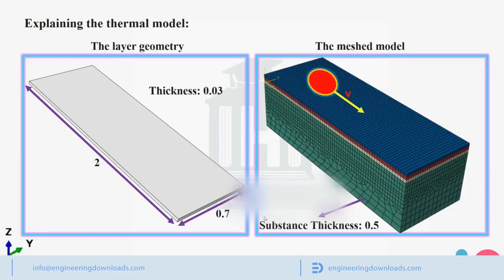In case you face a convergence problem in thermomechanical analysis, a possible option to fix the problem would be using the decoupled method. Since the analysis is performed via the decoupling method in this video, after we successfully complete the heat model, we need to create a mechanical model with which to predict the mechanical behavior of the simulation.